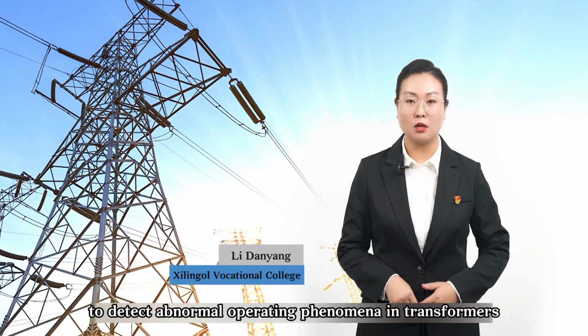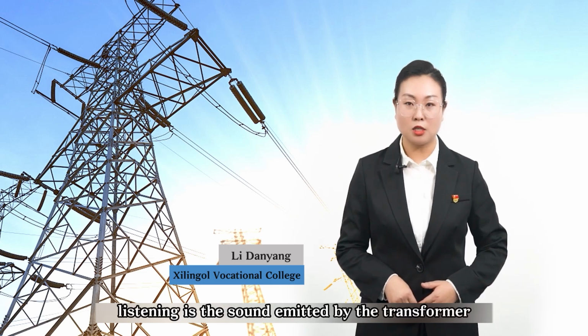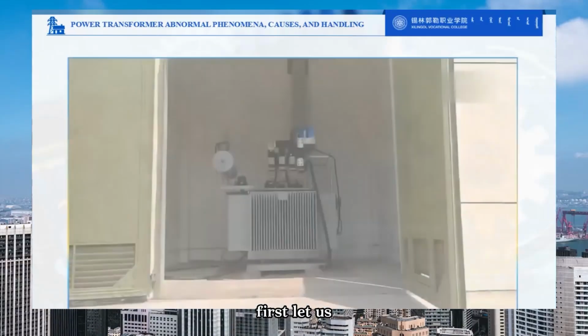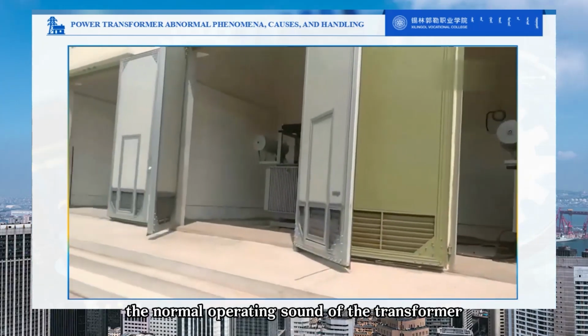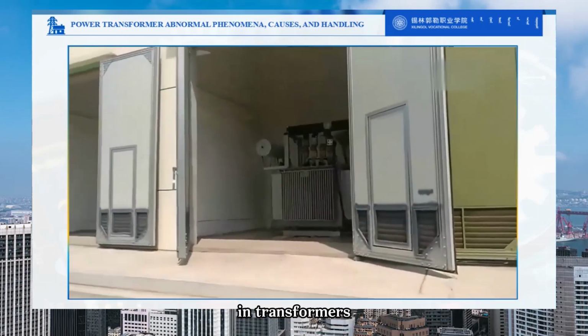To detect abnormal operating phenomena in transformers, we mainly rely on two words, listening and looking. Listening is the sound emitted by the transformer. Looking mainly involves observing the oil temperature gauge, oil level gauge, oil color, etc. First, let us listen to the normal operating sound of the transformer. Students, knowing the normal operating sound of the transformer can better distinguish abnormal phenomena in transformers.